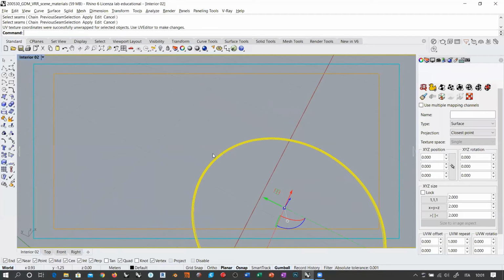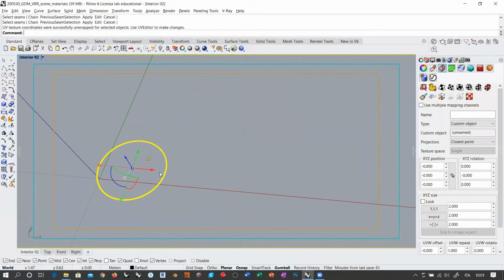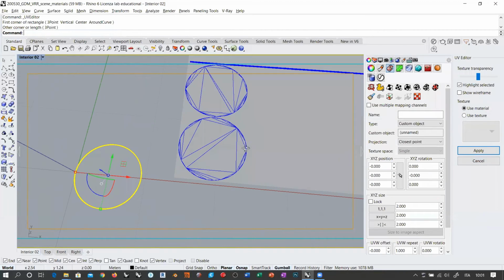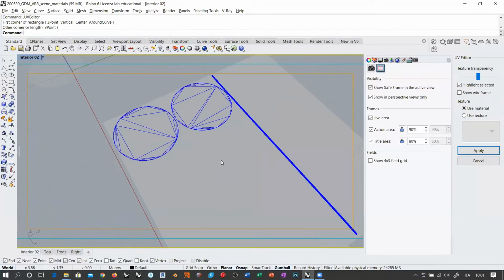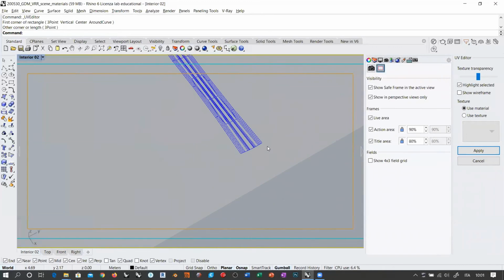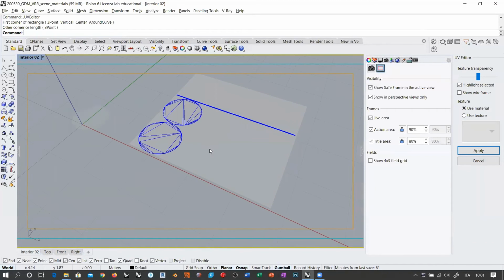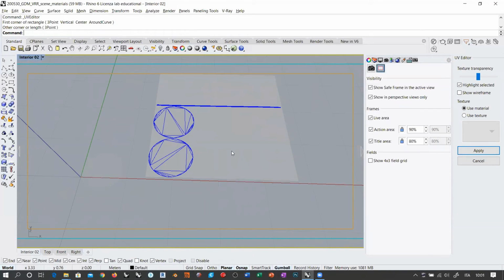So this is the rule that I want to use for the seams, and then I open the UV editor and draw this, and now we have the same two circles, but if we take a look, this is actually more regular than before. You see, it's a single stripe. Okay, so first things first, you must define the cutting edges for the seam edges properly, else you will get an irregular unwrap and you will be in trouble.